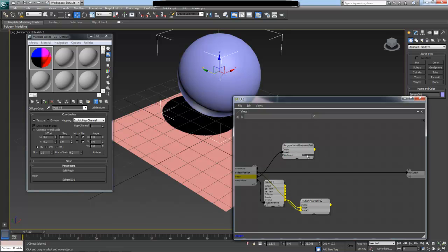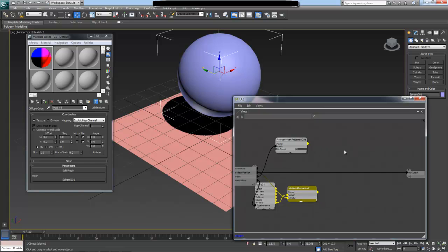I just changed the bin count to 10, but this can be any other value, and it's just an internal calculation value that we shouldn't be concerned with in this video. Next, I'm going to get the type value for this projected grid object, and inside of this I can see that there is an output called isInside. This is a function which accepts a coordinate and provides a Boolean output, which is going to be true whenever this coordinate is located inside the mesh, and false otherwise.